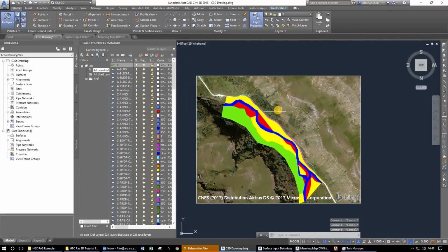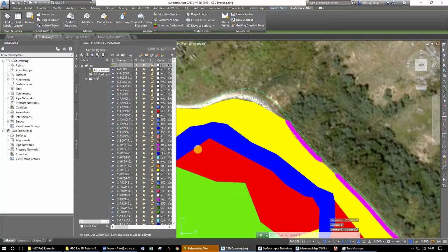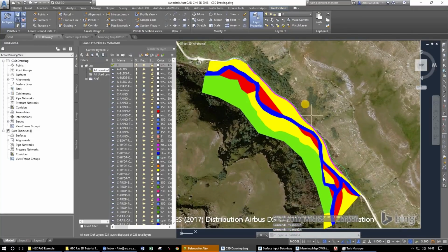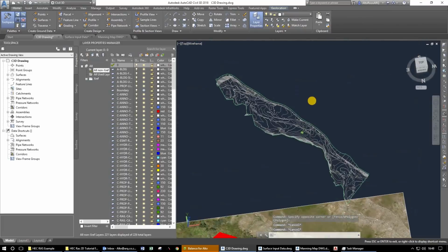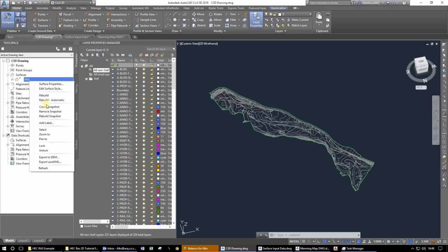After we've done this, we need to start exporting the specific maps that we've got. Firstly, we will have to export the surface and then the different Manning regions. Once we've done that, we can import that into HEC-RAS. For now, let's just start by exporting the surface. That's done by going to your tool space, surfaces, right clicking on the specific surface, and then we can say export to DEM.